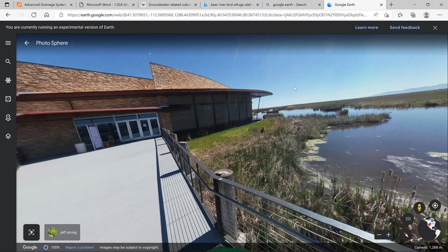And we're like, oh man, what's going on? Anyways, the groundwater came up pretty dang quick. I don't remember what phase of construction we were in. It seems like we had most of the foundation backfilled and some of it not, and so we started to see the water table start to rise. Quickly got a new pump in there, but I think the lesson learned for me was, man, always have extra pumps. If you're doing dewatering, you need to have more than one pump that works.